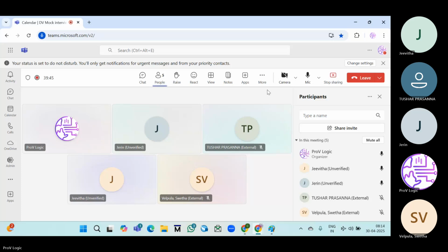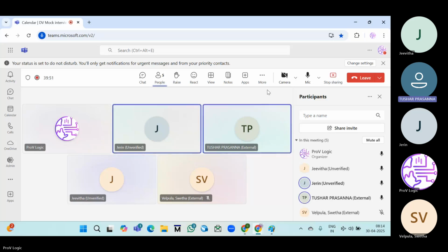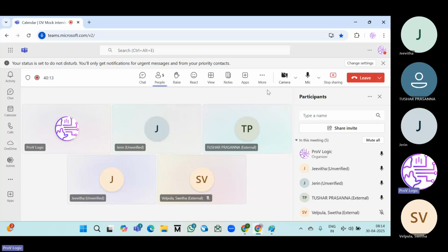Tushar, synthesizable are like wire, registers that are actually converted to the net lists, and then non-synthesizable are like integers. I'm not sure about integers actually, or parameters or constant definitions that we write in the code. Those are non-synthesizable. What about time, real? They are also not synthesizable, which we use only in the test bench, right? Okay. Next question.